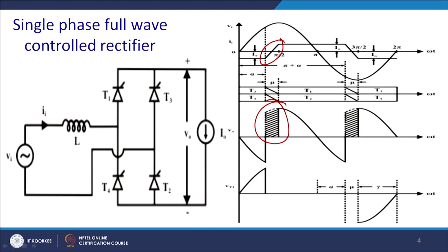It is basically the conduction of both the thyristors for some interval of time. So, mu is the region where you can see that T3 is going on and T4 is going off. For this reason this overlap region comes, and this is the voltage blocking capability of the thyristor till Vt1, at an alpha it will block.